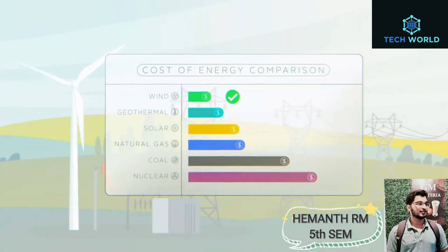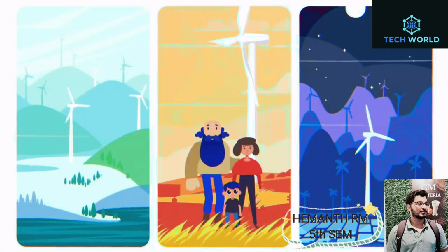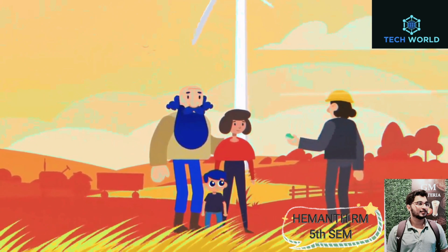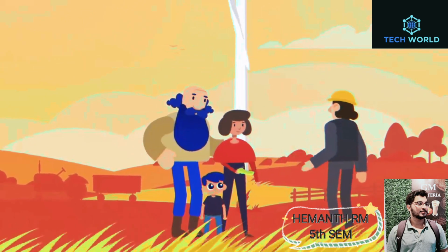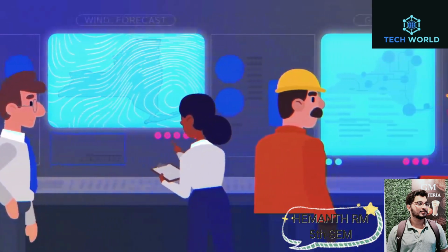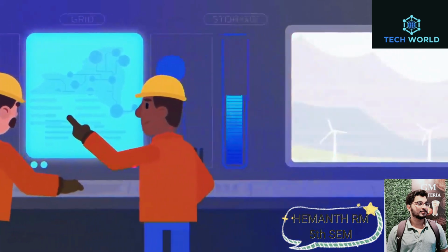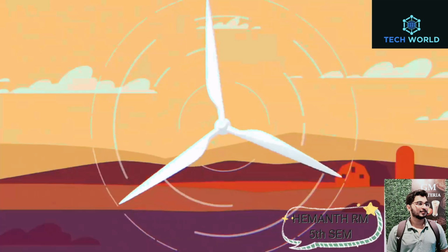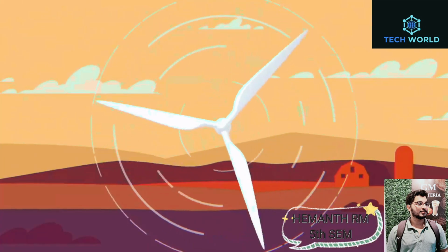Despite its amazing potential, wind energy still faces challenges. Wind may be a free and unlimited fuel, but no matter how large or efficient a turbine is, it is mathematically limited in how much wind it can convert into electricity. German physicist Albert Betz calculated that since some wind must remain to keep the blades spinning, a turbine can only ever capture 59.3% of it.